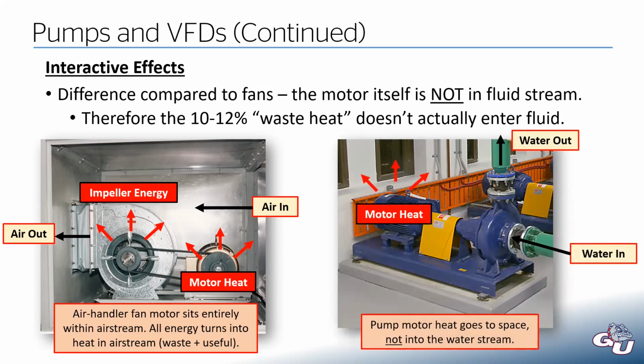And that would be a correct argument to make. But when we're isolating our focus on the hot water system, that motor heat is not entering the fluid stream. So we would only have the impeller energy going into the fluid stream, that 90% of the motor input.